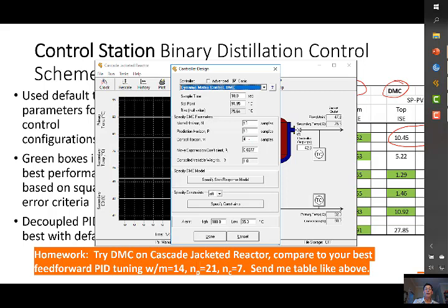the model horizon, M in your textbook, M for model, is 13 samples. The prediction horizon, N sub P, is 13 samples. Well, that doesn't meet the criteria we just talked about, being 1.5 times M, but that's okay. And then the control horizon, N sub C, in the discussion we've just had, is 4 samples. So we're going to predict 4 moves in the future and implement the first one.